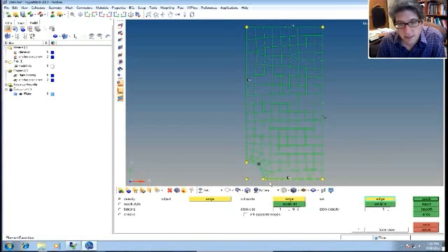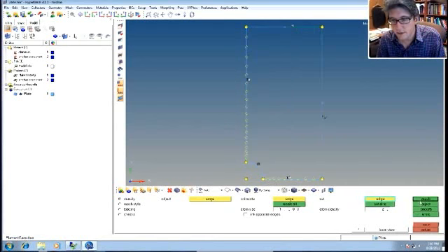There it goes. Now we set that to 10. And maybe we should bump this up. Instead of 16, we can make that like, let's make it like 20. Well, yeah, let's do 20. So put 20 on that edge. And then we can do a reject. And we can mesh it again. And that looks kind of nice.